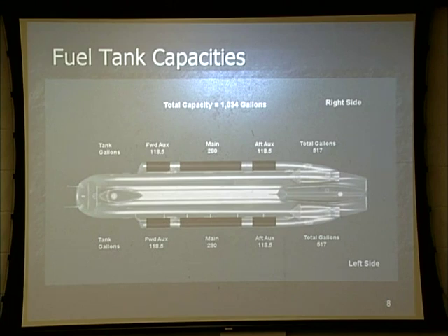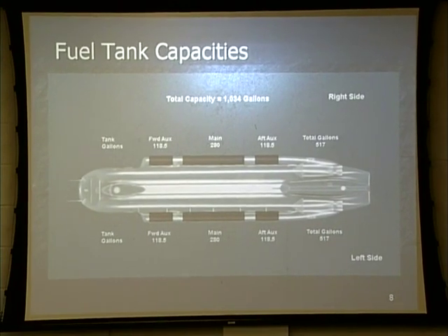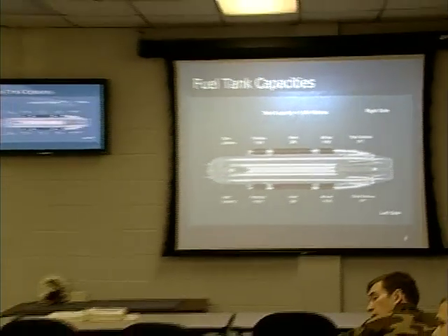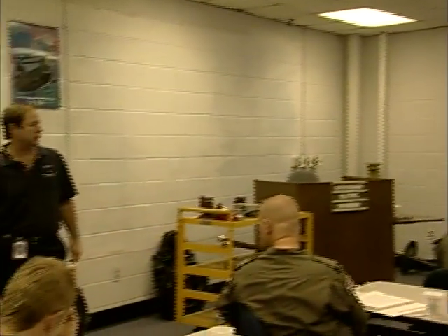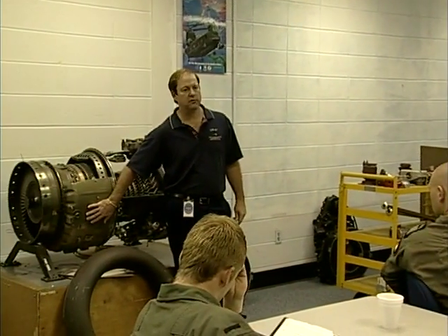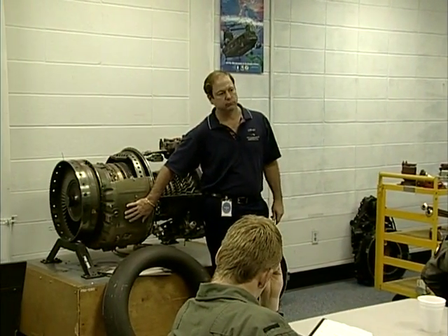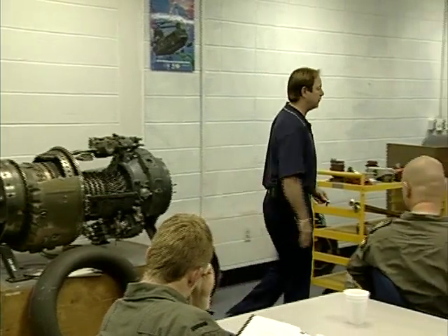What does my operator's manual say about low lead? 6 hours. Now, keeping in mind, why? Even though it's low lead, it still has lead. And what will happen if we allow it to accumulate is that lead will form deposits in our combustor chamber, resulting in hot spots, which is why we're limited to 6 hours.